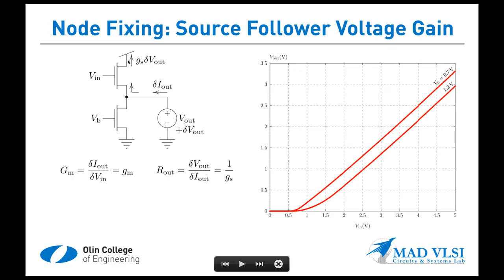And so there will be a quiescent current that's always flowing from drain to source here, but we're going to represent a reduction in this current as an increment flowing against that quiescent current. Okay, so that's something that takes a little bit of getting used to, but it's a very useful way of thinking about the current increments and how they flow through the circuit.